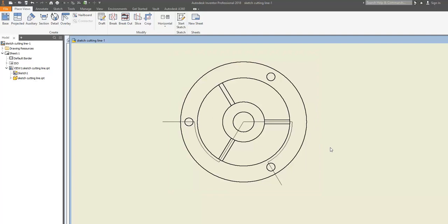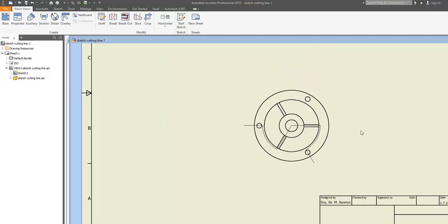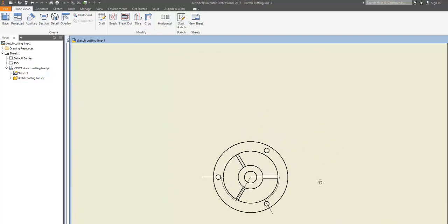In other words, apply the revolve process to bring the drill from here to the place at which the radial axis is as if parallel to the picture plane, and while keeping the body stationary, rotate this rib till making its surface parallel to the picture plane. It is the picture plane on which the sectional view is needed. Okay, then we can start the sectioning process.